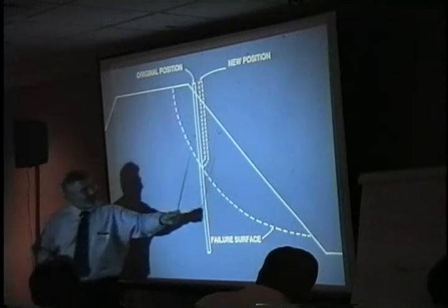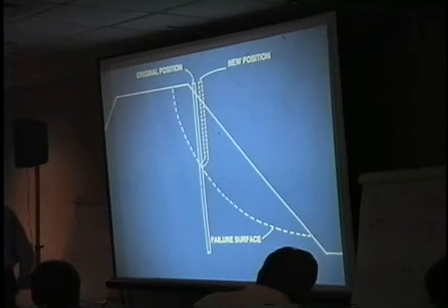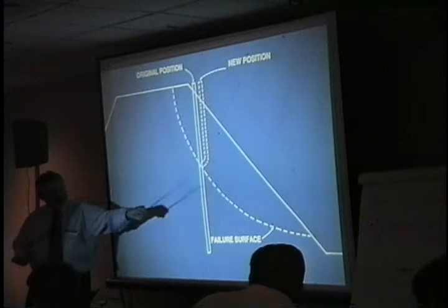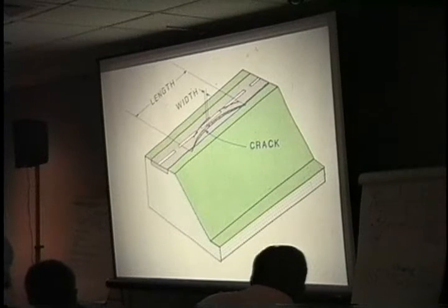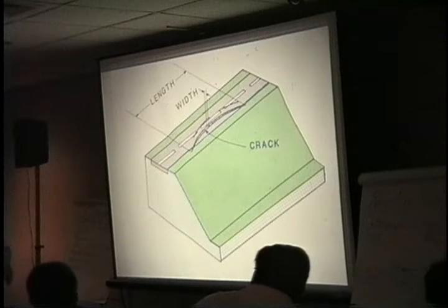So if you want to put in a couple of inclinometers, even before, you may only see a tension crack, but if you see other signs on the slope, it may tell you this could be a bigger one, and since it's been moving and drag patch put on the top for years, maybe it's time to do a further analysis.